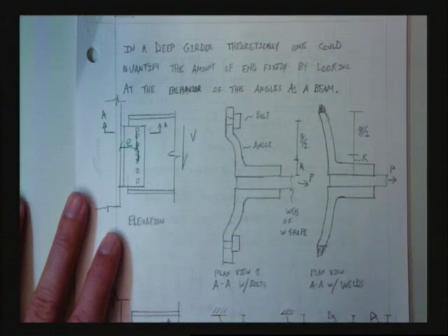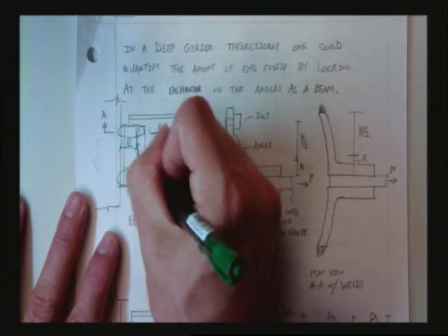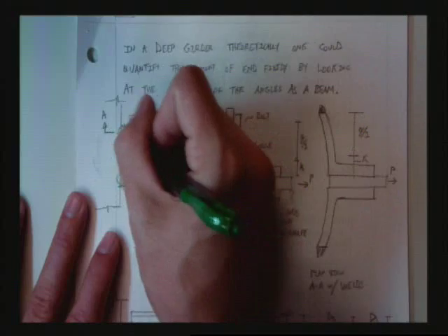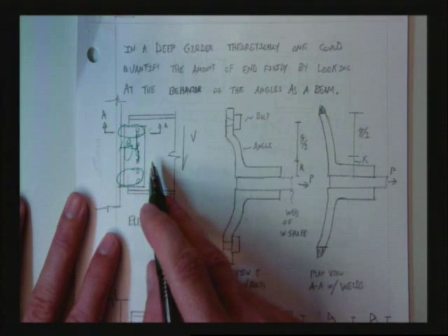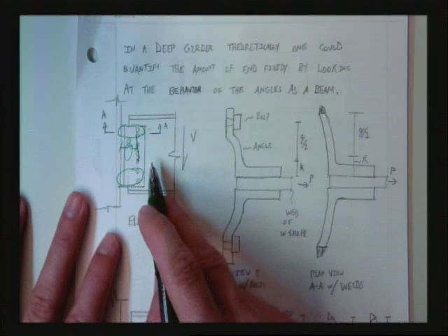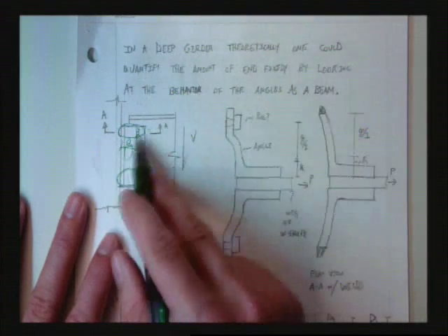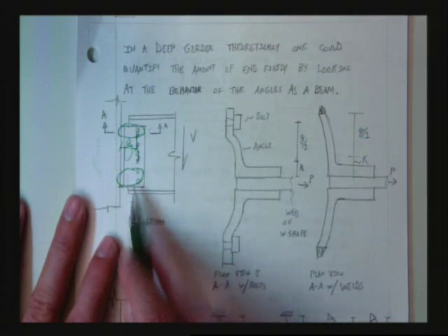And then when the load transfer happens, the load transfer is happening up here, and the load transfer is happening down here, the moment load transfer, and the shear is going to be transferred in the middle. Now we're going to assume shear is going to work. It's just another check. It's not that big of a deal. Shear is a check you'd have to do no matter what the connection was. Everybody with me on that? We did homework on that. Now we're really wondering, do we have the stiffness and the load capacity for this couple? That's what we're trying to work on now.